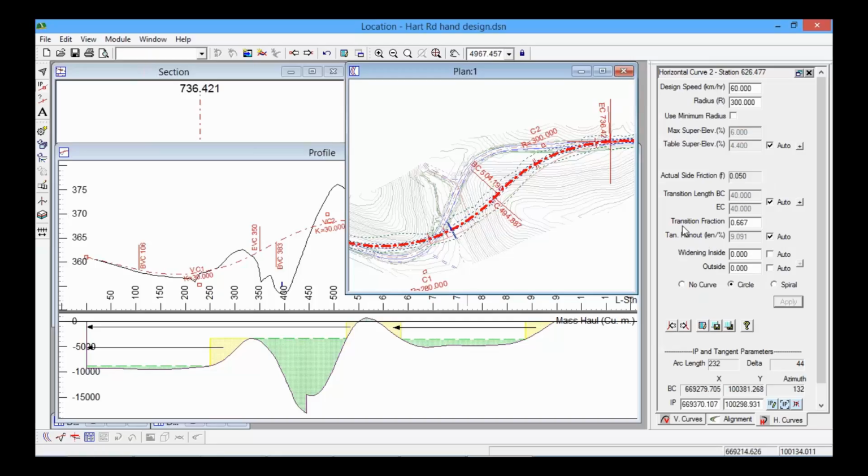In our link to Civil 3D, we're going to take the cross sections right out of the Civil 3D software with a little add-on, and so all of those parameters that define things like final slopes and super elevation and so on won't even be in this software. It'll just pull the cross sections directly.